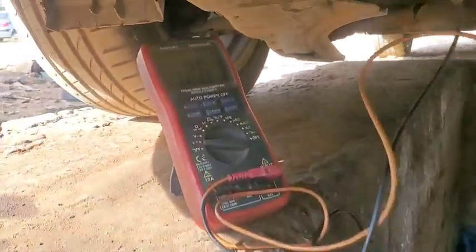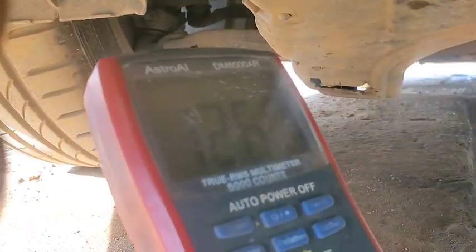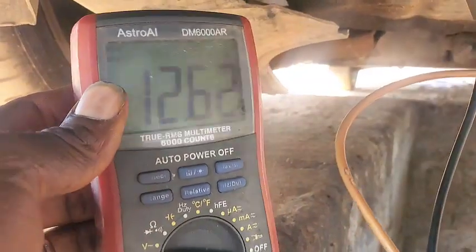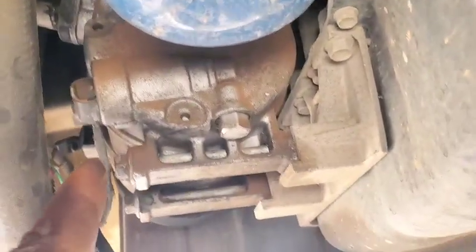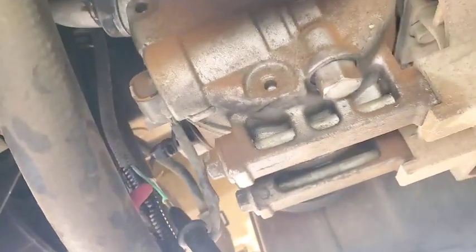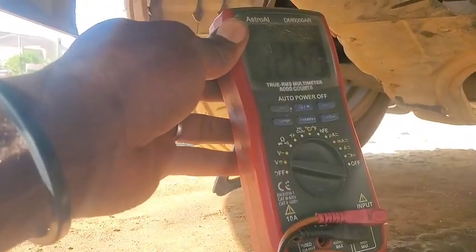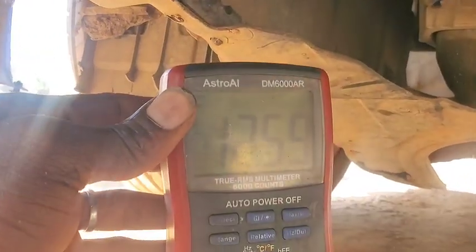Let me show you, because I parked in the pit here where I'm taking the voltage readings, since I can't see it through the live stream data. Over here I've hooked up my multimeter, and you can see the power that connects to the solenoid control valve, which is underneath, in this pit here. You can see it right there. I tapped on the power going there, and be careful if you're tapping like this so that you don't short circuit it. The power is pretty much consistent, going between 12.5, 12.6, 12.7.